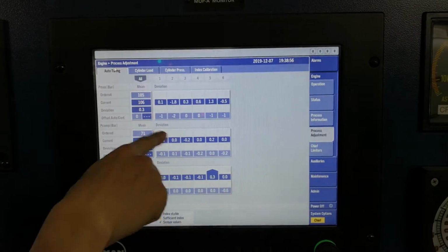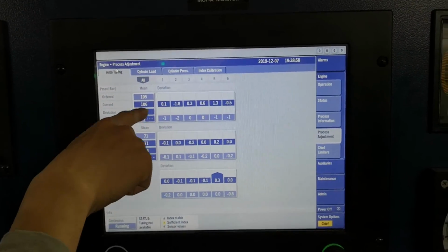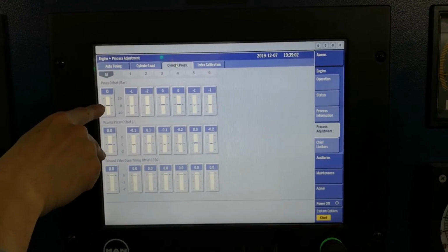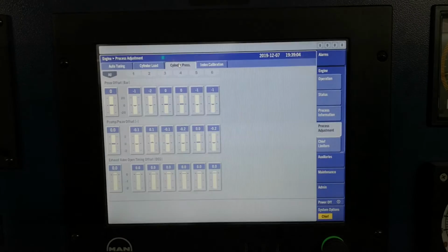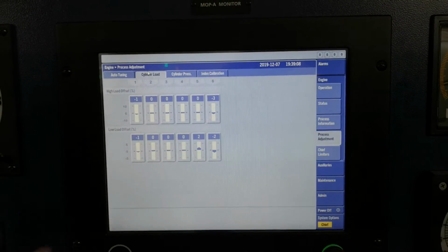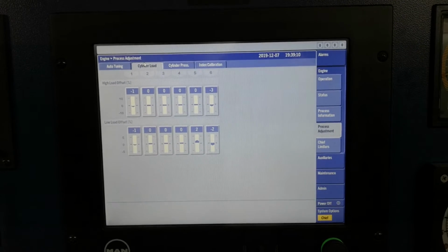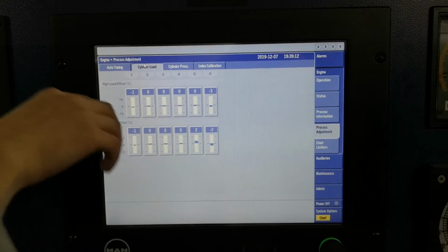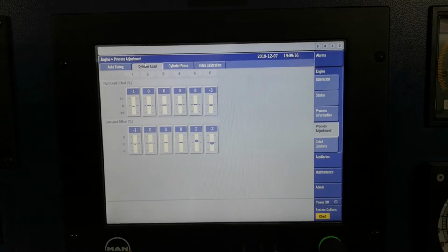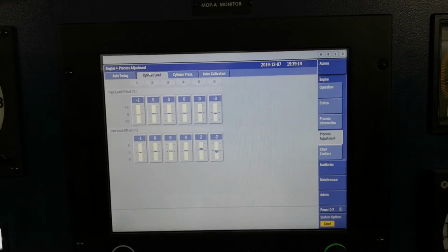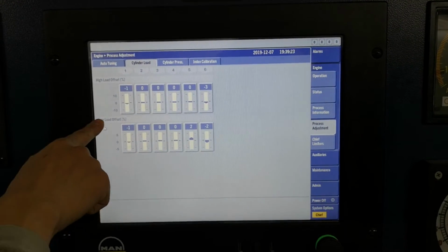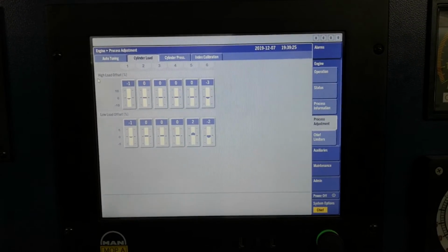If you use this auto function, auto tuning adjusts here. Also, you can find that this value is automatically adjusted. So you can have a chance for manual or auto. This is a PI value, which simply says the amount of fuel injected. If this is plus, more fuel, which means the exhaust gas outlet temperature will be higher. Correct.